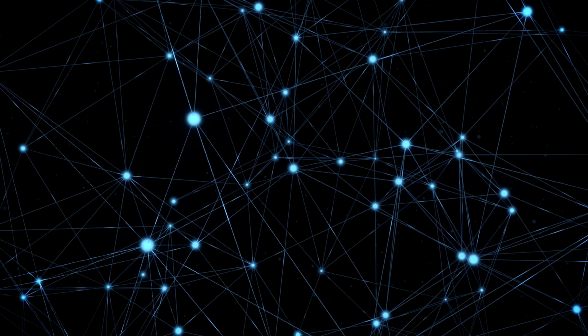LWDM isn't as well known as, for example, CWDM or DWDM, but there's also a big difference in how they were actually specified. For CWDM and DWDM, the number of channels in each individual grid was specified right from the word go. But with LWDM, that wasn't the case. It evolved over the course of time and the number of channels increased. If you want to find out why that was, and also what LWDM is used for, stick around and we'll check it out.